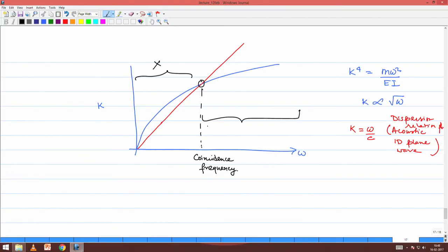As has been reported in the literature, this is what we call the coupling between the vibration and the sound. As I said, without proof at this stage, the sound radiation for a given vibration happens only for frequencies beyond the coincidence frequency.